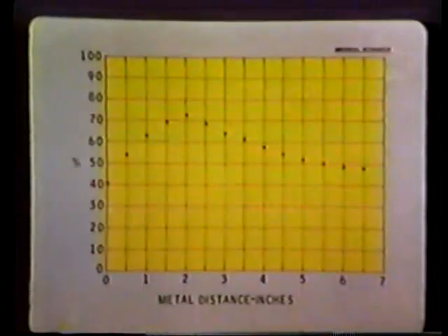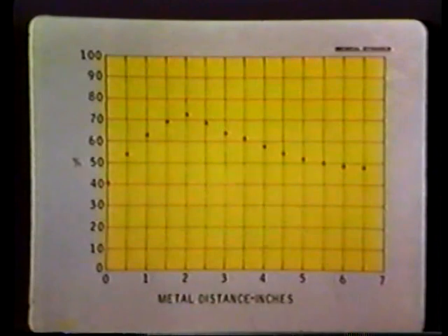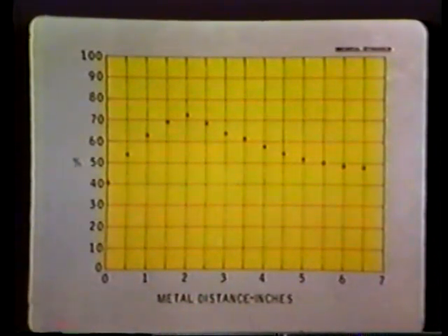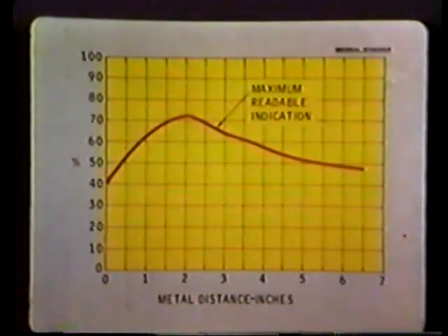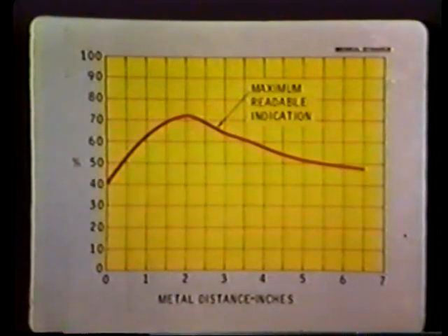Readings are then recorded for each of the remaining blocks in the set, using the same gain setting, maintaining the same water travel, and so on. Once the response curve is plotted, equipment performance can be verified simply by taking 2 or 3 readings and comparing them with the curve.